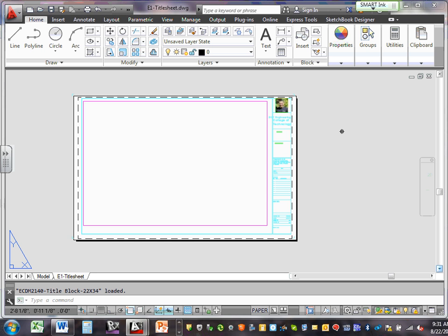If it doesn't, and you know that you edited your title block, this means you edited the wrong title block. It happens a lot. If you have two title blocks and you edited one of them, but it's not the one that you XREF to, so what would you do? If you're in this situation, then rename the one that you edited with the same name as the one that you XREF, exactly the same name. Delete the one that you XREF, and it should populate it.